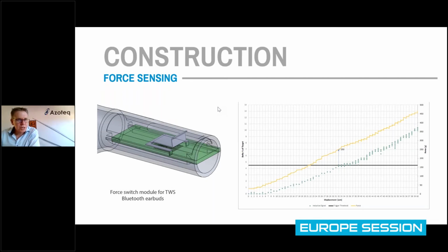Then Eugene has a second question, whether it's possible to measure humidity. Eugene, we can detect a change of humidity with capacitive techniques, but humidity has very little influence on inductive sensing. So the short answer is that inductive sensing is not a suitable measuring technique for humidity. So no.